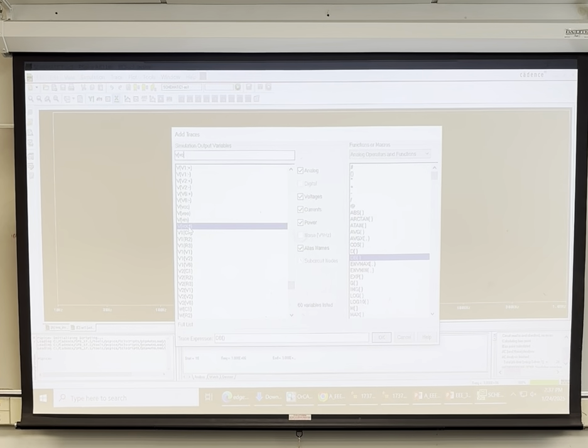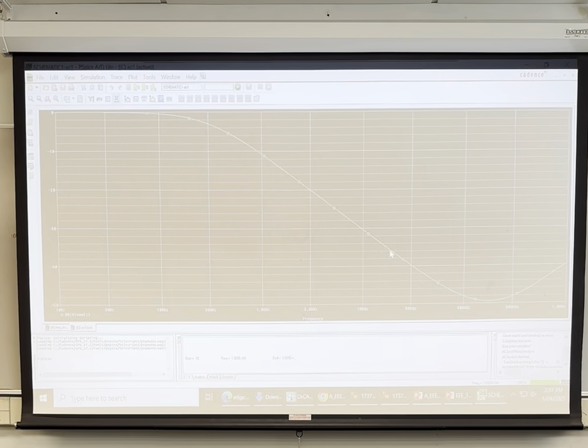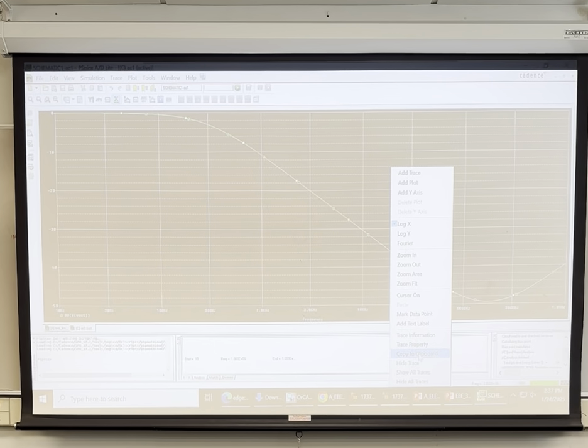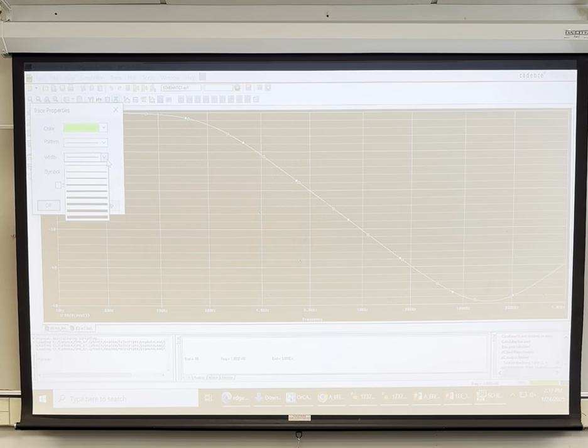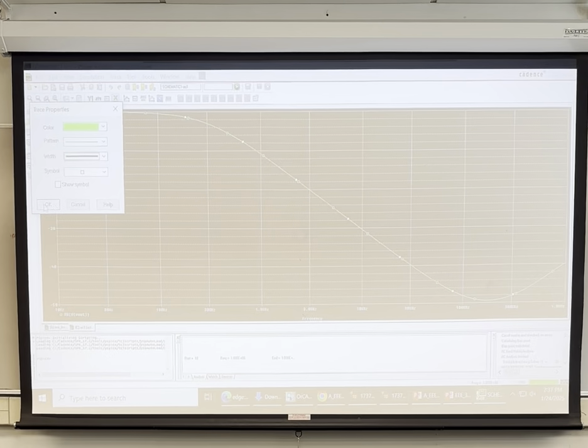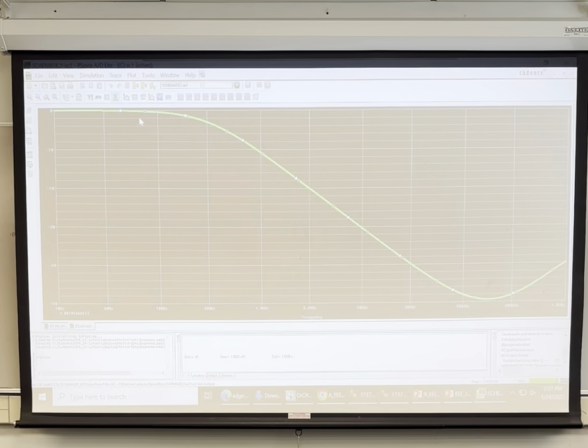It's actually V out over Vn, however Vn is equal to 1, so you can leave that off. And so there's the plot. So once you get the plot, probably will widen the plot slightly. And again, now we go back and we'll check to find out if the 3 dB is anywhere near the cutoff.